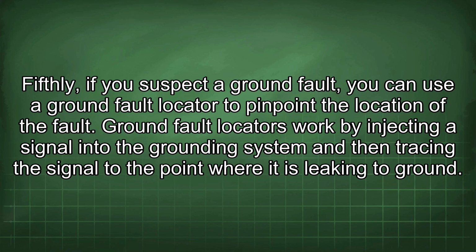Fifthly, if you suspect a ground fault, you can use a ground fault locator to pinpoint the location of the fault. Ground fault locators work by injecting a signal into the grounding system and then tracing the signal to the point where it is leaking to ground.